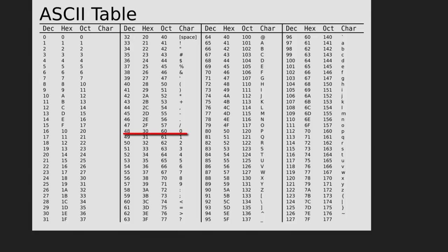If we wanted to be able to go all through the upper and lower case and have them as different valid commands, we would have to have a very large command table. We'd have to go all the way from 30 all the way up to 7A hex. So you can see that just with our simple comparison of making sure it's within our command table, we have to have all of those bytes even if we're not using them.